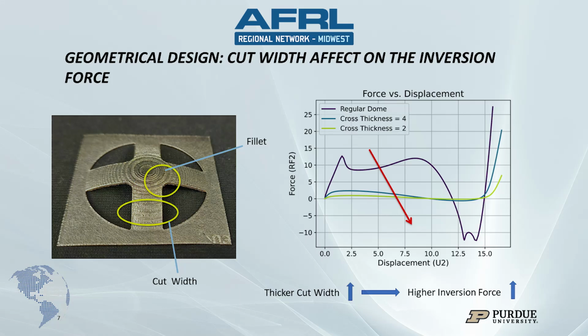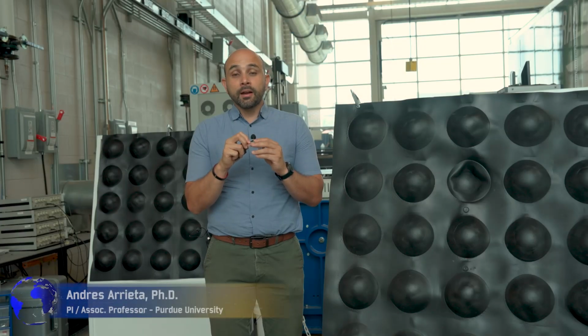The process to obtain designs that reduce the amount of strain that the units undergo when being snapped requires the use of some mechanics of shells combined with fabrication and finite element results. Our initial steps determine that by cutting out parts of the dome, we are able to reduce the amount of strains that the structure undergoes when snapping. Effectively, we're reducing the points of stress concentration that occur due to the inversion of the dome units.